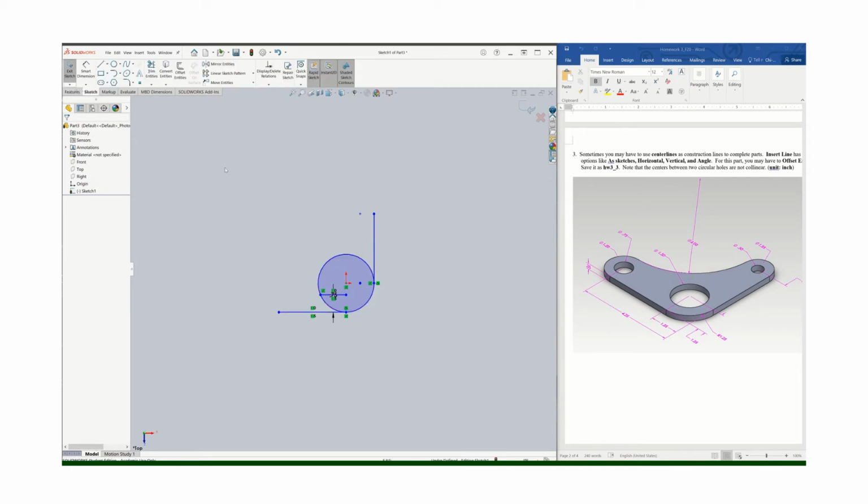Then with this, I could have an offset of this line, the offset of that line, in the opposite direction by 0.625, because the top edge, that rounded edge, has a diameter of 1.25, so that should be 1.25 over 2, that's 0.625. So that's what I want.